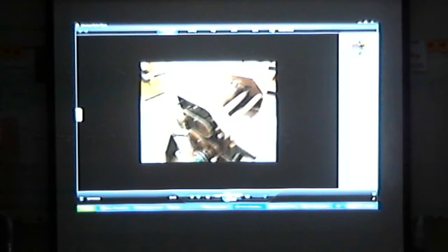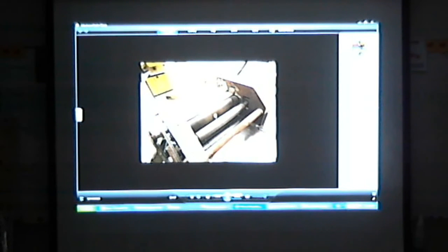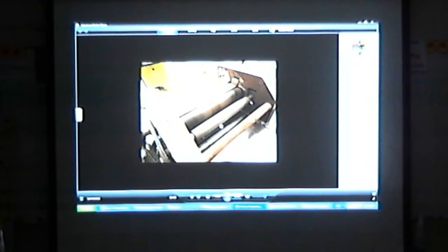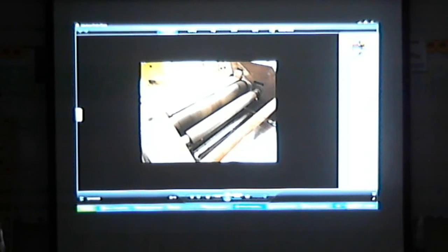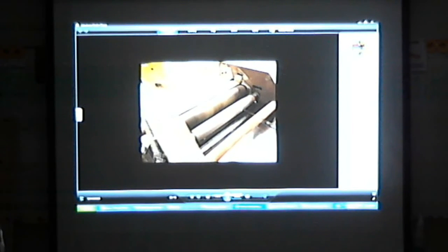Okay? So the only way to get it out is to shut it off, wait for it to come to a complete stop, lower it, and then grab it out. And it's also a potential for a kickback. And you guys can see how fast it's spinning. So this again is the cutter head. You can see the in-feed roller again. Sorry, this is the table, in-feed roller.